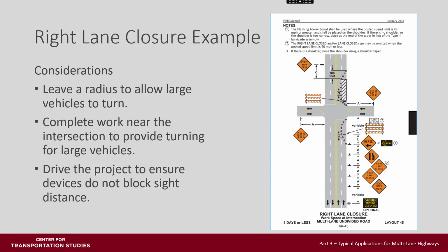Part 1 of this series detailed the need to keep accurate records of temporary traffic controls used along any roadway and any modifications needed for that particular location. The need to conduct a drive-through to see the work zone from the driver's perspective is very important. Some considerations for this strategy and layout are: leave a radius large enough for turning vehicles from the major road in from both the cross street directions.